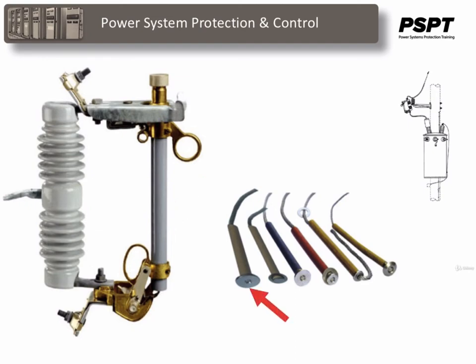Ferrules are usually attached to the fuse element that goes inside to make the connection to the outer circuits a lot easier. The fuse link, the fusible element connecting the two line terminals of the fuse holder, is usually a composition of material that depends on the speed required and the interrupting capacity, and is made up of several alloys or materials that the manufacturer can offer the user.